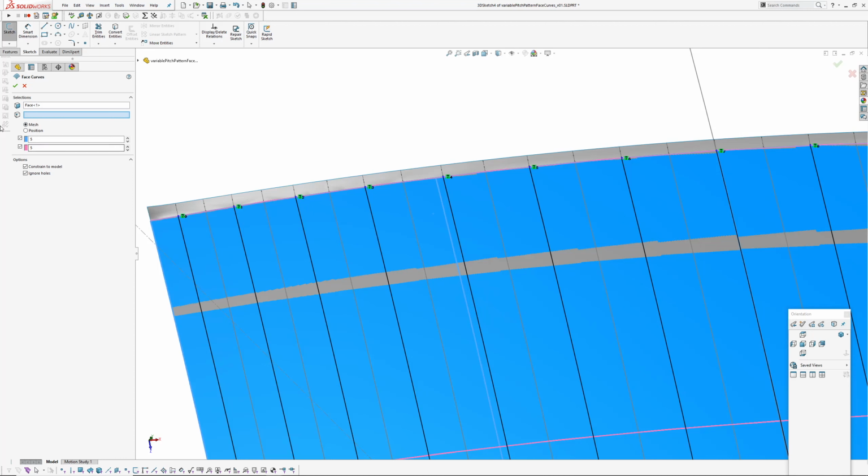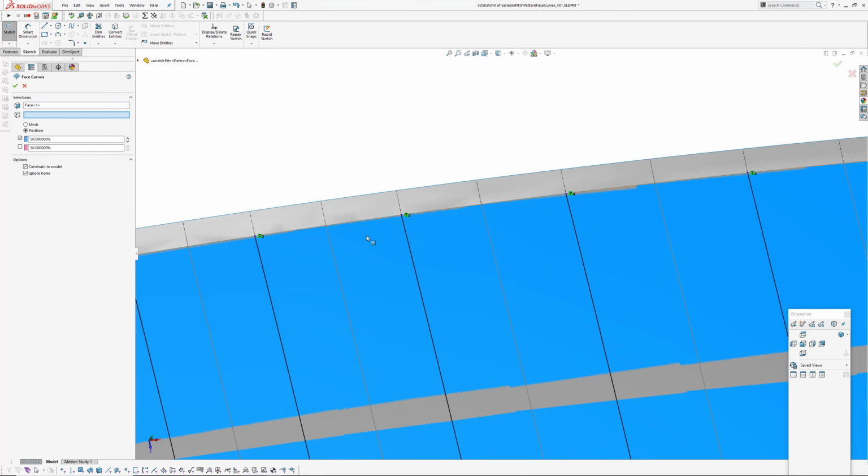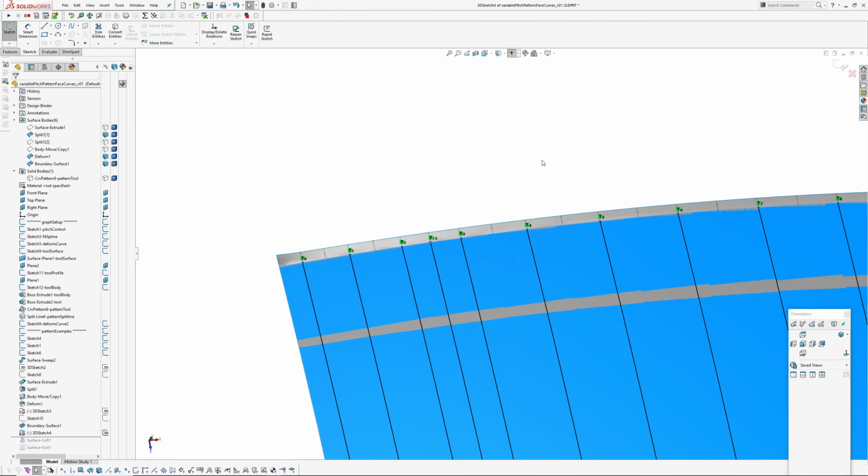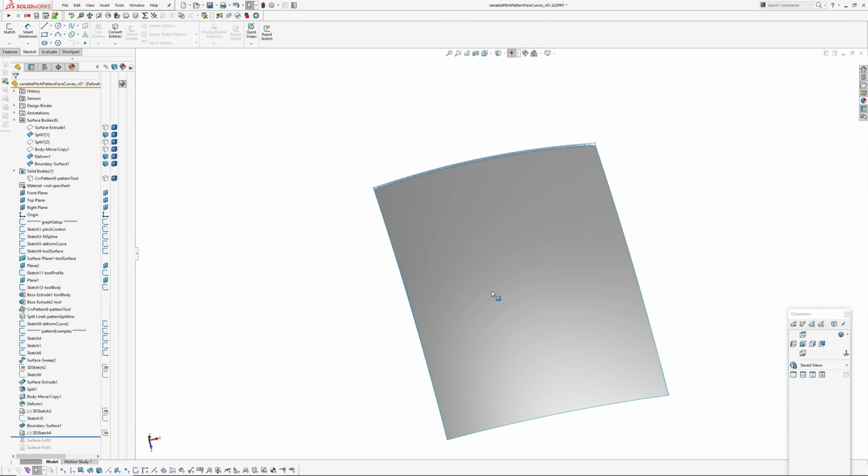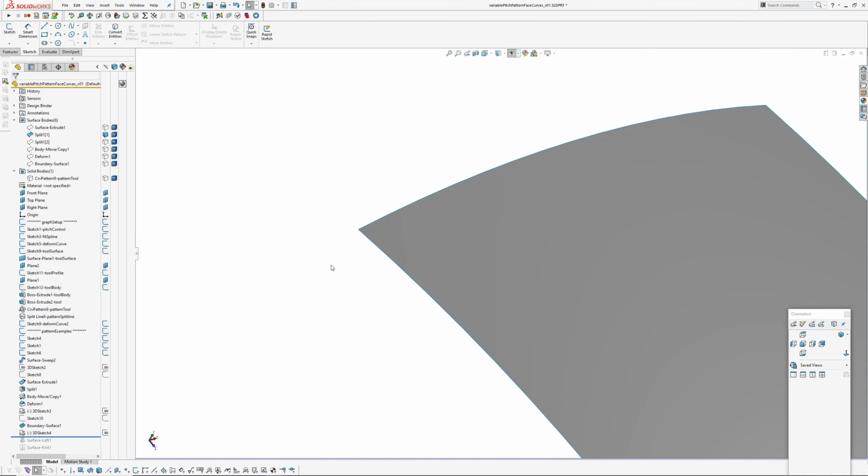In this case I want to keep a blue one, so turn the pink direction off, UV direction, and then pick a position, and then instead of using a length ratio, I'm going to pick a vertex, like so. Okay, so I just repeated that across. Okay, so now I'll hide these surfaces.